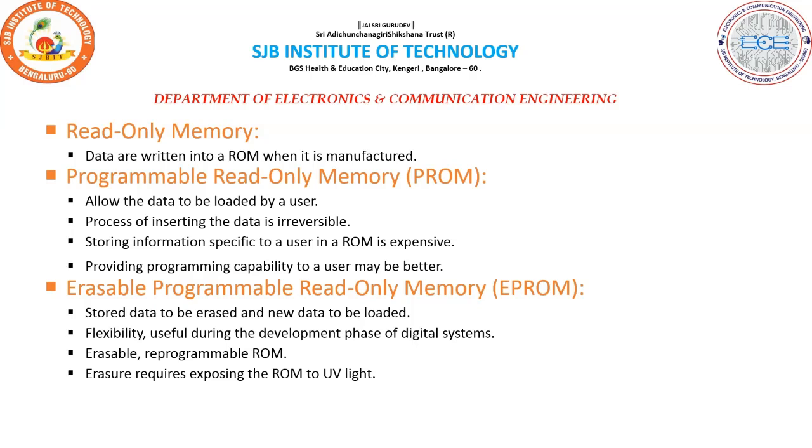Another memory is known as the erasable programmable read-only memory, EPROM. It allows stored data to be erased and new data to be loaded. This flexibility is useful during the development phase of a digital system. Erasing the reprogrammable ROM requires exposing it to UV light.